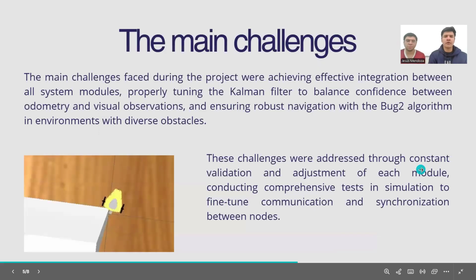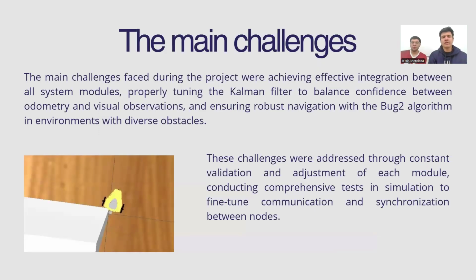Okay, during our challenge, we faced a lot of different troubles. For example, the integration between all system models, such as the Kalman filter with the odometry node and also the path generator, and we had many troubles in all those different simulations. So these challenges were addressed through constant validation and adjustment of each model. We made a lot of different simulations and we tried to correct our mistakes.